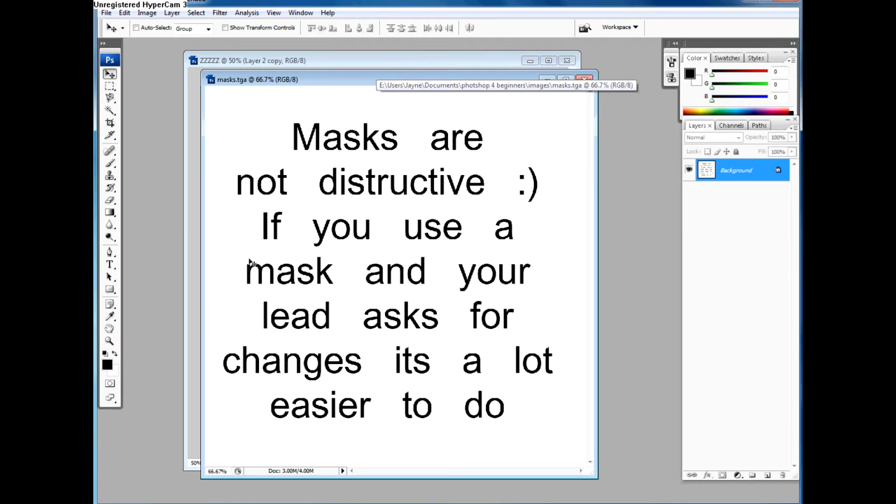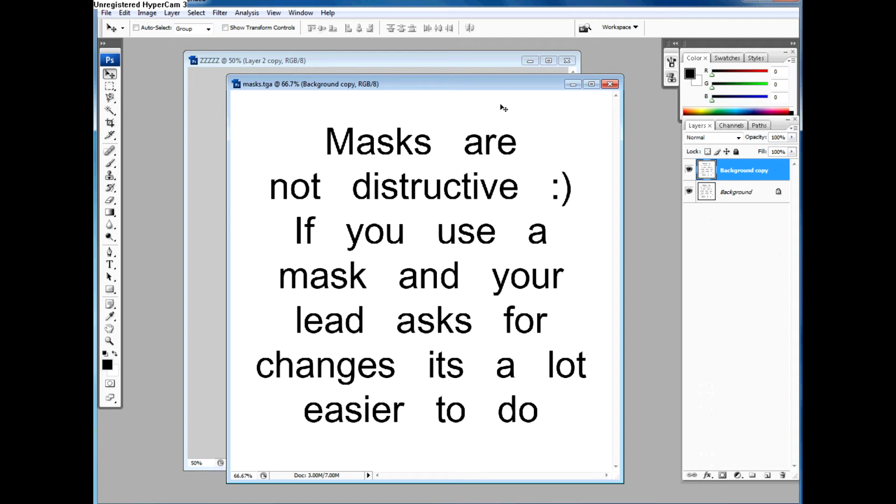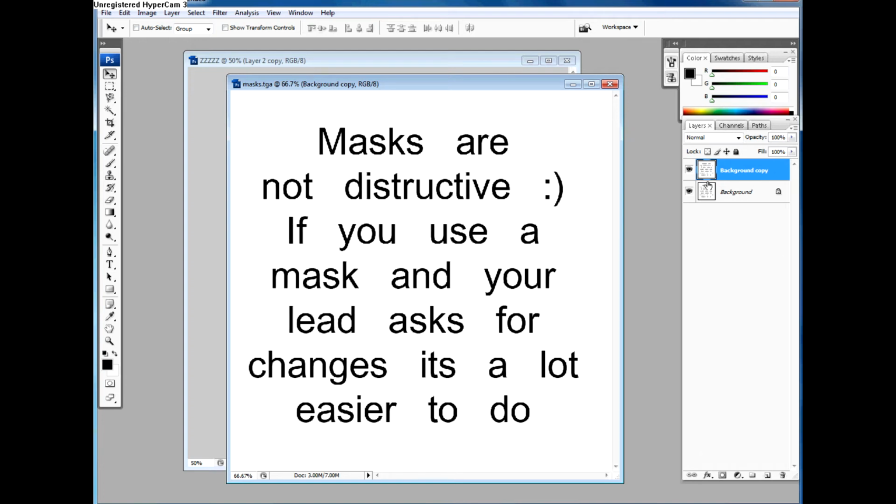So I've made a quick text layer and I've collapsed it. I just wanted to show you, I mentioned before about creating alphas and that kind of thing. So if I'm doing a plant, for example, for a game, I want to create an alpha channel. For that, again, as I said, the black you won't see and the white you will see. So in this scenario, I've got black text and a white background. So if I save this out on an alpha channel, I wouldn't actually see the writing, I'd just see the background, and there'd be a void where the writing is.